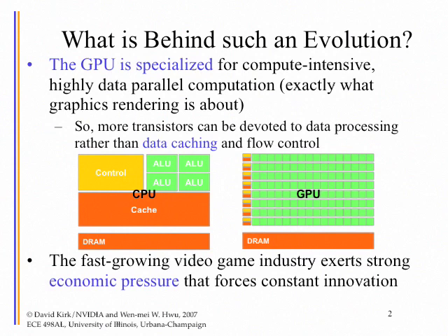Whereas the GPU design is based on a somewhat different philosophy. It says, I'm going to design the equivalent of a CPU core with a very small amount of memory. So I'm not going to try to put a lot of cache memory on the chip. I'm just going to put a small amount. And so whenever I execute, I'm going to have a little bit of control, a little bit of cache, and then a huge number of units. This was the SIMD thing that I was talking about, right?